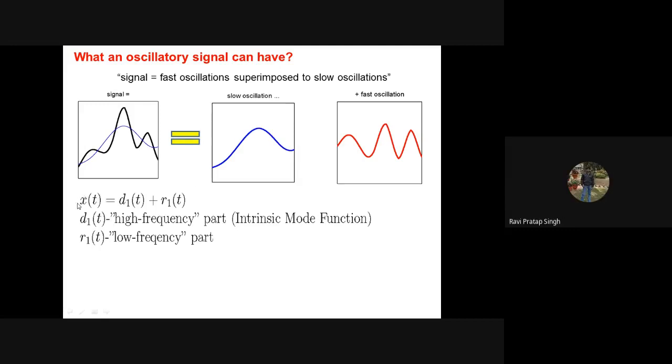So as such, the test signal we can have as a high frequency part, which we will refer to as intrinsic mode functions, and then another one as a low frequency part, which we call the residue here. So I will explain later in the slides. Now this decomposition of the original signal into intrinsic mode functions at several levels, and then finally obtaining the residue, is actually an iterative process here.